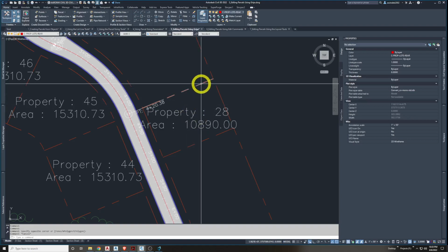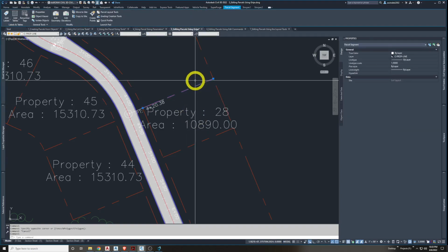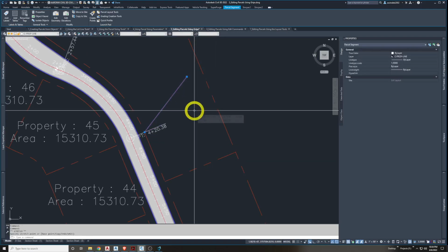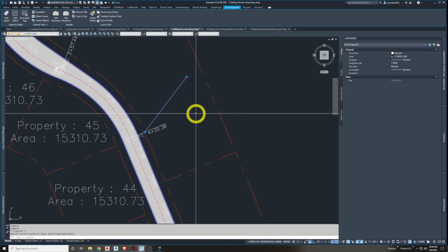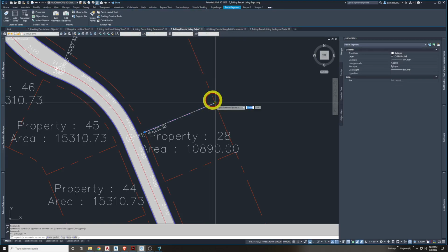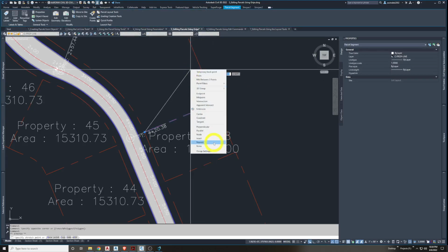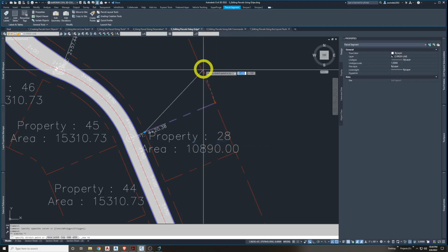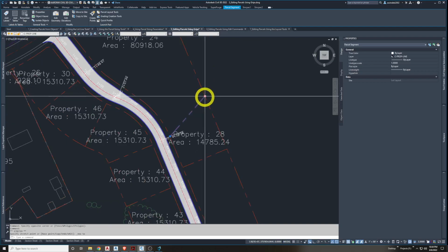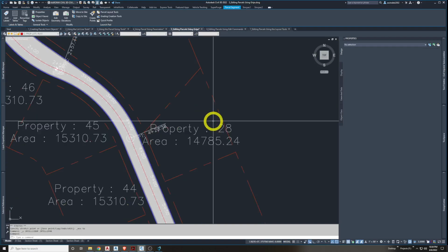We'll start with grips. They're easiest to get. We pick the northern part of property 28. We can simply move the parcel. That kills it right there, which we don't want. I'm going to hit Control Z to undo that. But maybe we keep the grip to something. If we do nearest, we keep it right there. We have to keep it intersecting some of these lines. Basically, it just says click on a couple various things, which I'll go back. I'll undo this, Control plus Z.